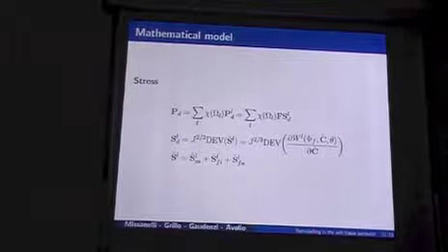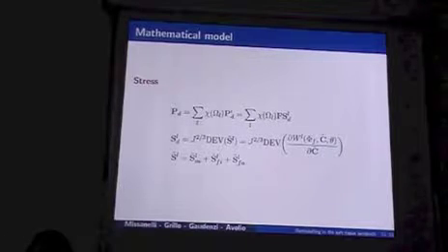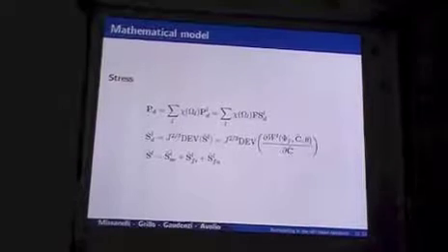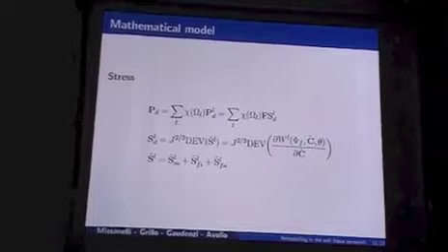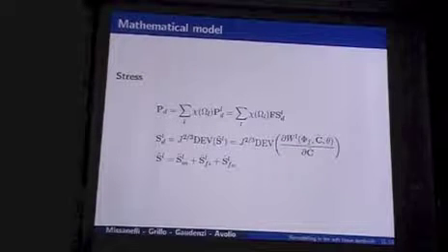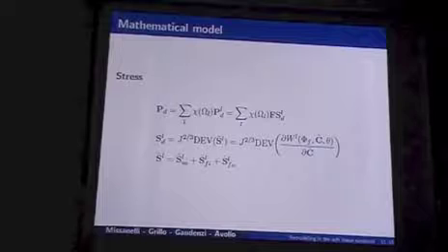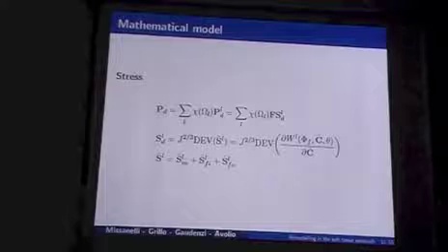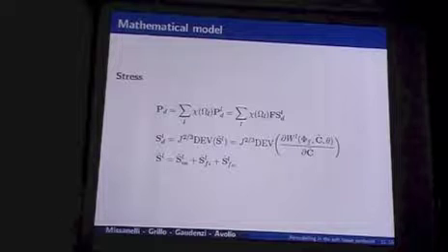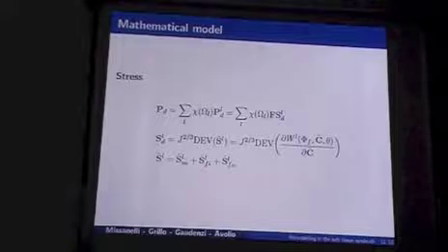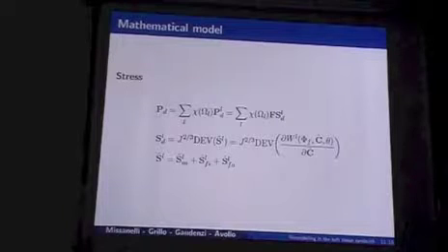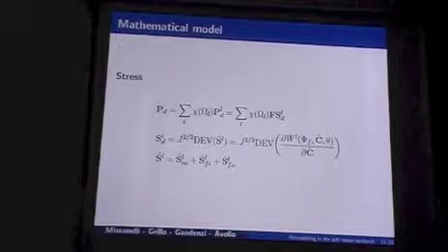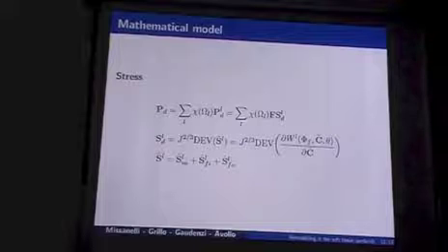For the deviatoric part of the first Piola-Kirchhoff tensor, we split the contribution of the layers. So we have three contributions: the media, the adventitia, and the dermis. Each contribution is viewed as the deviatoric part, like the derivative of the energy function. So we can use the split of the three components: the matrix, the isotropic fiber, and the anisotropic part.